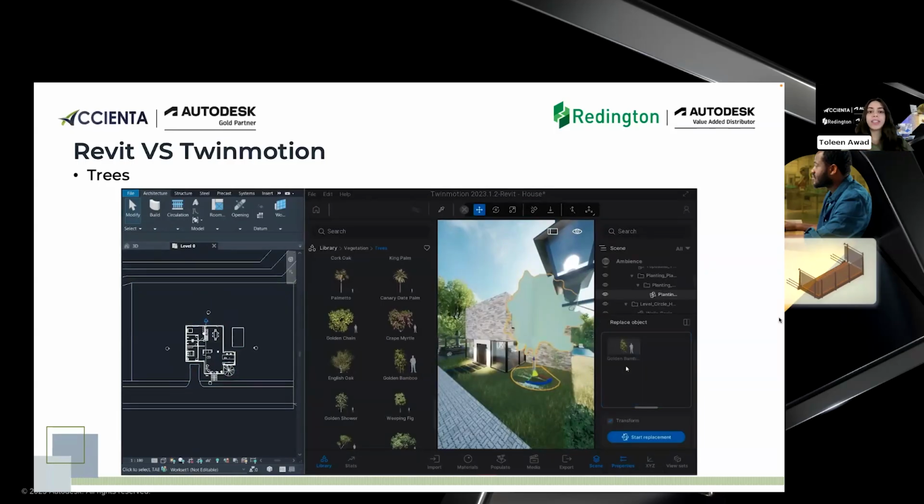You can go into the library, scroll down, choose whatever tree you want, and then choose to replace it. We can also change the age, the season the tree is in, how tall it is, and the width of the tree. You can choose whatever vegetation you want, and with one simple link we can see how we replaced the object that we added from Revit in Twinmotion itself. And if we go to the next video,